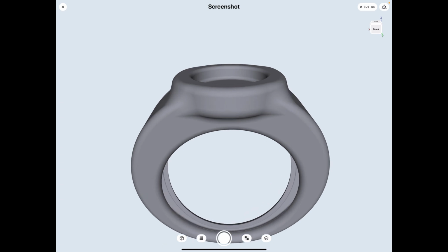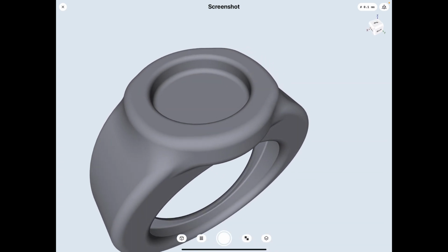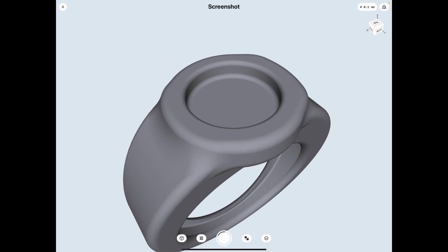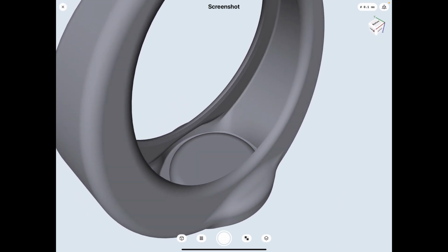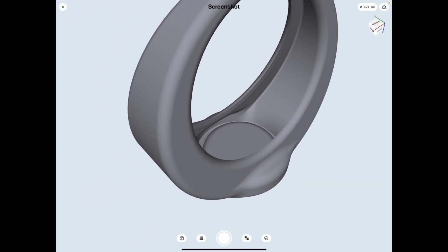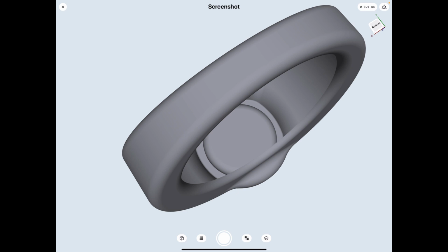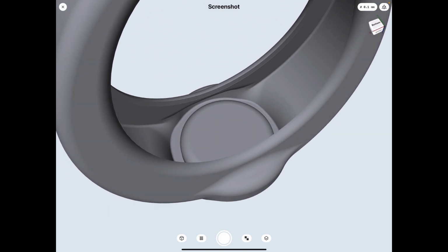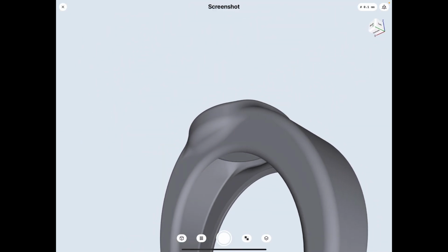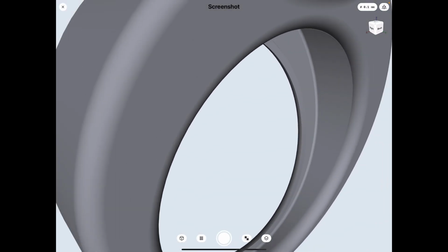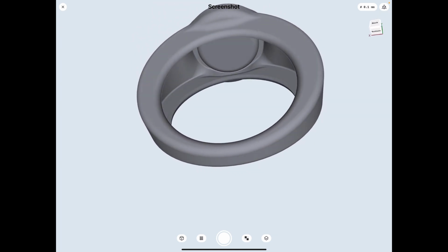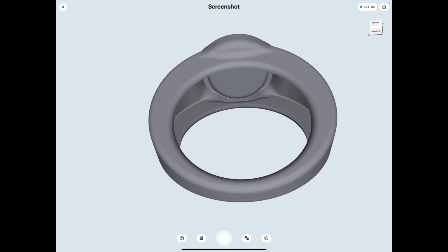You might want to do this if you're working in gold, like high carat gold, and cost is an issue. Just using less is sometimes best. For casting, you do have to think a little bit more ahead when you get into thin walls like this. 0.75, very, very thin. I would definitely not want to go under a millimeter if I could, but this is a software limitation that it just spat out at me unexpectedly. So not always the best, but definitely something to consider.